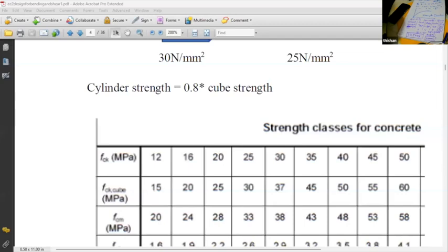So in pre-stressed concrete, there's no need to use fly ash, but sometimes for workability, because fly ash can give a huge improvement to workability. Because of that reason, sometimes engineers say, okay, I'd like to use 10 or 15% fly ash. In pre-stressed concrete, what is most important is the early strength. So if you need high early strength, don't use fly ash. But if you run the risk of DEF, then use fly ash.